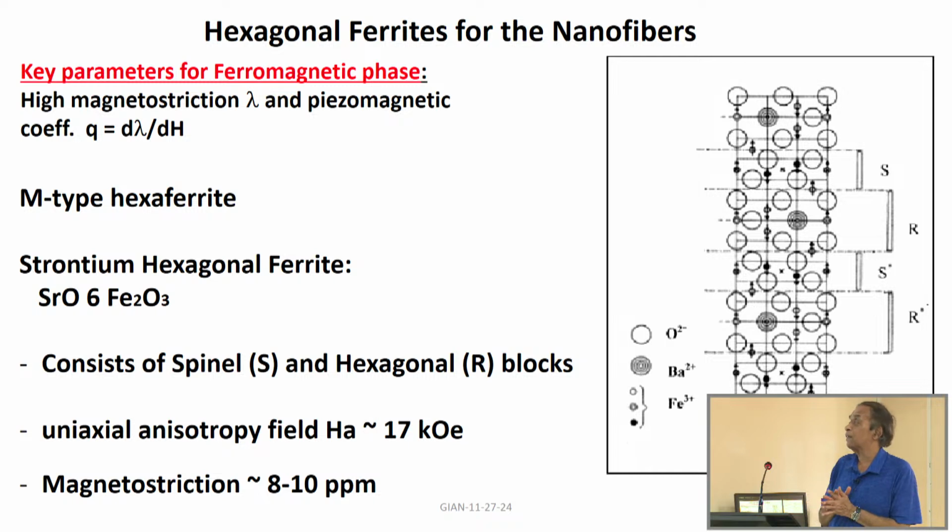But what you need to understand is there are certain types, and they are associated with the presence of a very strong magnetocrystalline anisotropy. So, in these structures, there is significant spin-orbit coupling. It is coupling between the spin of the electrons and the orbital motion that leads to locking the magnetic moment in a particular direction. So, that is what we mean by magnetocrystalline anisotropy.